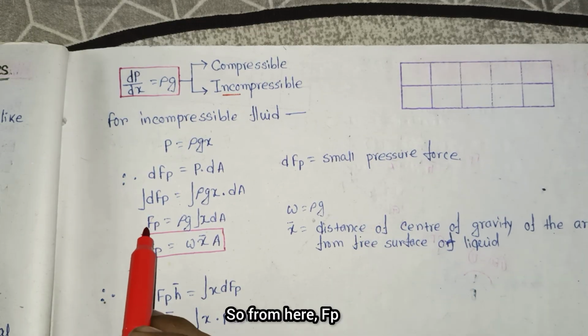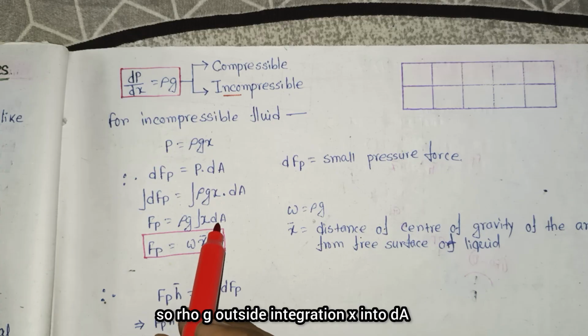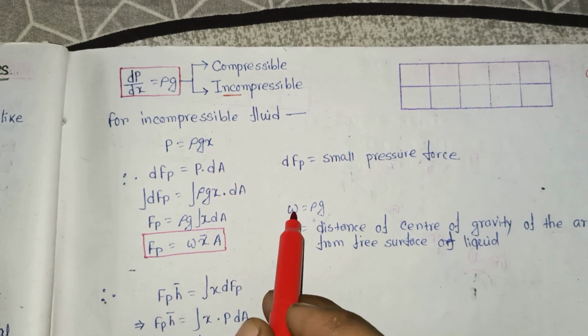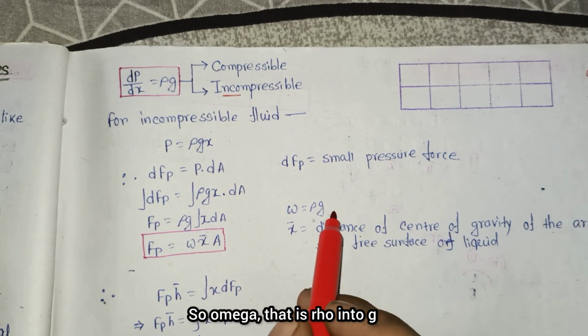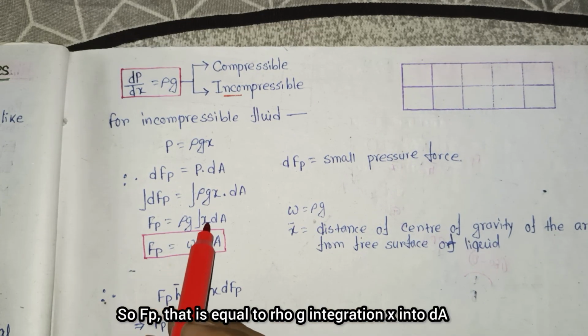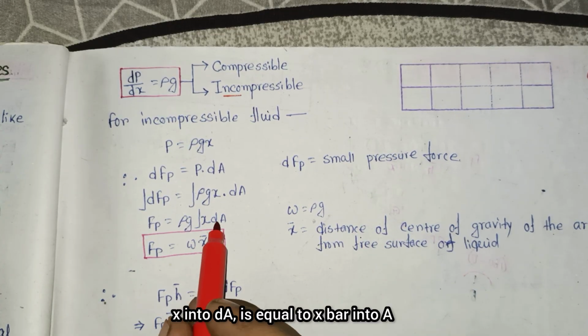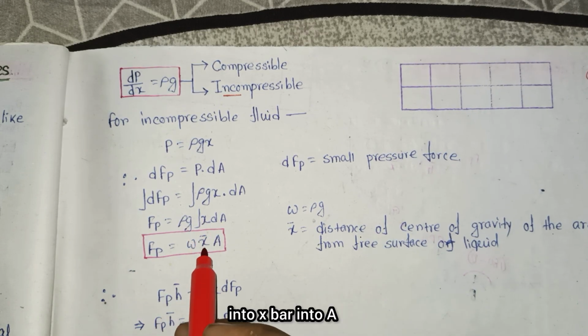So FP is equal to rho g, which is a constant, so rho g outside, integration x into dA. We know that rho g is the specific weight, omega, equal to mg by V, m by V is rho, into g. So omega is rho into g. So FP is equal to rho g integration x into dA. Now this integration x into dA is equal to x bar into A. So FP is equal to rho g, that is omega, into x bar into A.